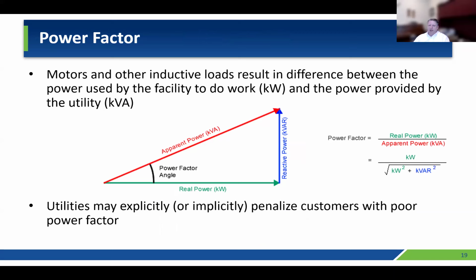Power factor is something you may also find on your bills. It's important to pay attention to this if you can. This is caused by motors or other inductive type loads, where some of the power that's being drawn or provided from your utility is going towards energizing the magnetic fields, whereas the power that you're actually extracting from that motor is going to be in terms of real power or mechanical power.